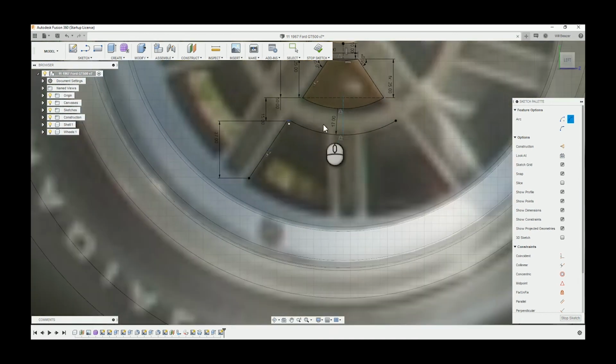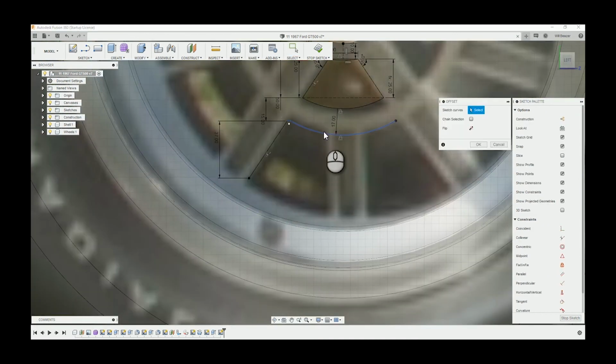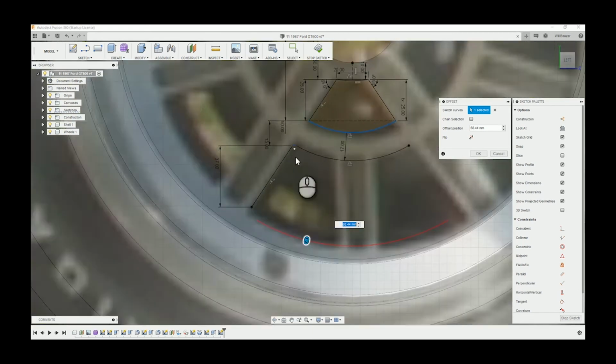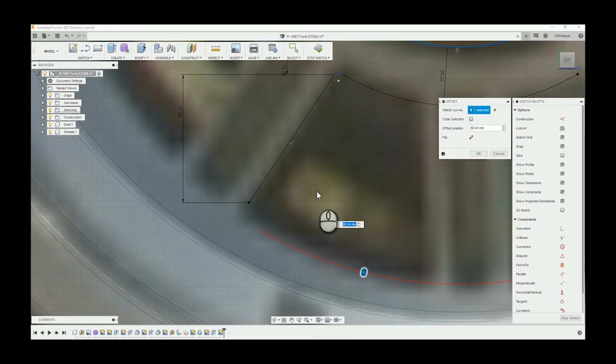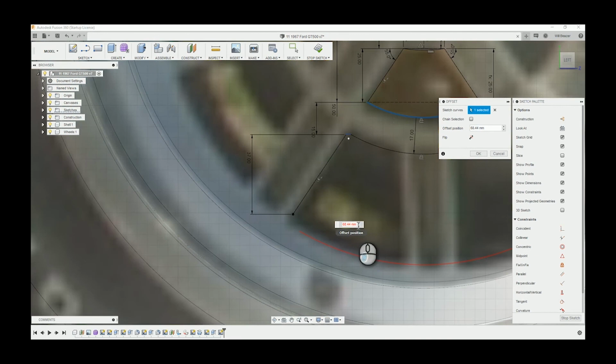So now I'm going to offset again, and what I actually try to do is offset that arc, and the problem, see there's an error in the bottom right. The reason why that's happening is you can't offset an offset feature, and the reason is it wouldn't make sense to anyway. Firstly, it would prolong your computing time if Fusion even allowed you to do it, and secondly, by offsetting an offset feature, there's plenty more opportunities for things to go wrong. So just offset from the same sketch arc that you originally offset the first one from as well. That was why that error came up.